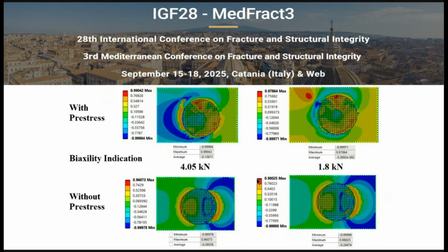4.05 kilonewton loadings. In spot welded structures, a spot weld is sheared under higher loads, while at the lowest load the sheets are usually just tearing.